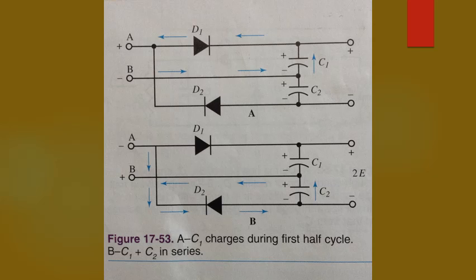Voltage doubler circuits provide useful high voltages for circuits needing low current. Because output voltage depends on charged capacitors, voltage regulation is poor. Conventional filter circuits are needed to smooth out the voltage as in transformer rectifier circuits.